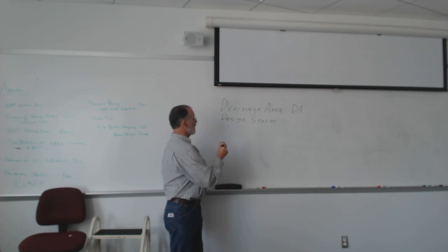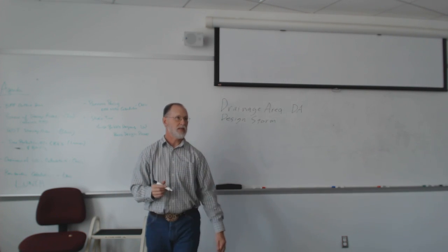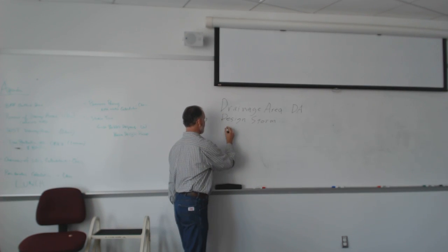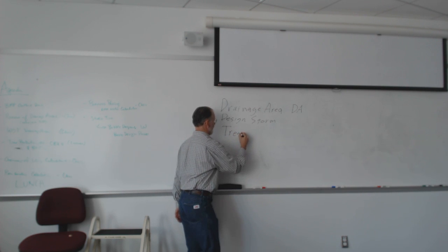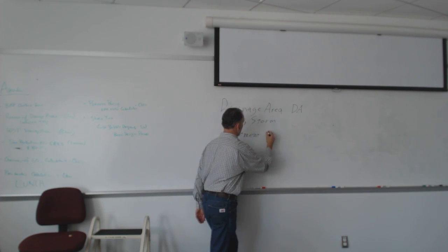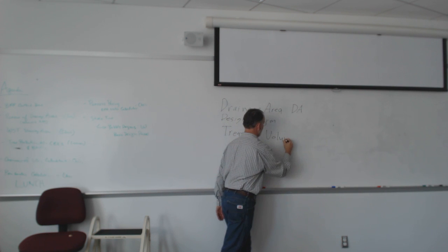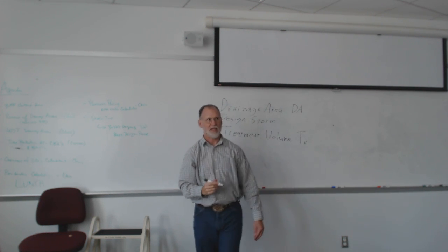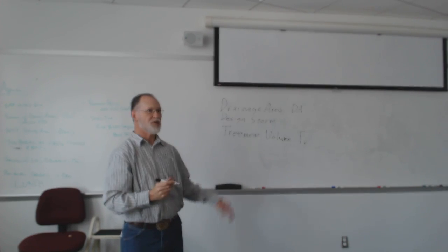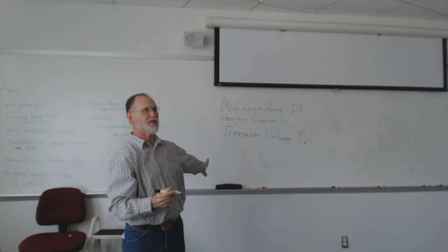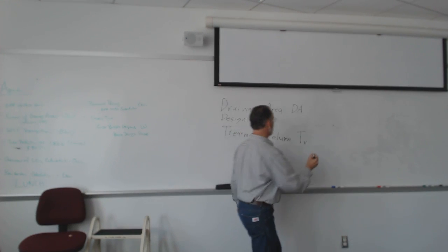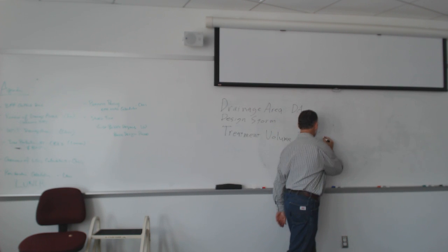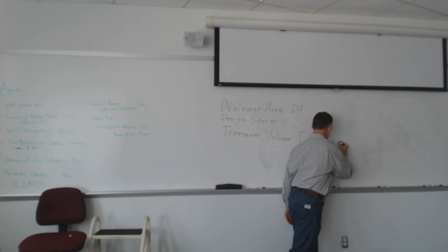We're going to need to know what is commonly called in the regulations the treatment volume. And in Virginia, at least, that's big T, little v. The treatment volume is what you've already been calculating. That is the runoff volume. That's what we calculated for the church project. So different name, same thing.